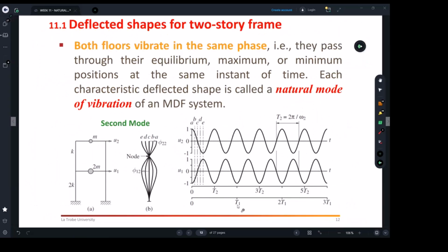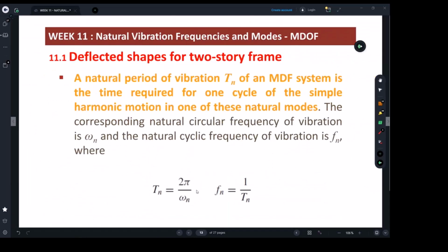And that will be reversed in the frequency. So here you're going to have a lower frequency than what you have for the second mode shape. That's the second outcome from our calculation. So it's actually the first one. When we start working on the math, the first thing we aim at is finding the time period, because it will tell us for the first mode shape, this is the time period. For the second mode shape, you will have another time period, T2.